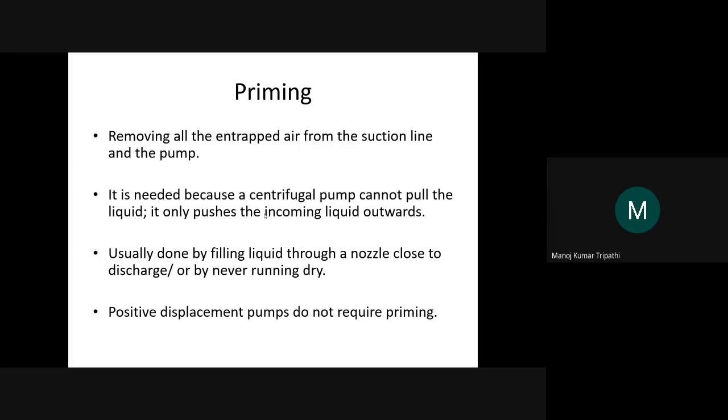So with centrifugal pumps, there is a problem. To solve that problem, priming is required. You may have this experience, or you might have heard this, that if a pump goes dry at home, let's say there is air in the inlet pipe, there is no water, then you need to fill water in the inlet side for the pump to run again. Otherwise, it won't work properly. So this process of refilling the inlet with water is known as priming of the pump.